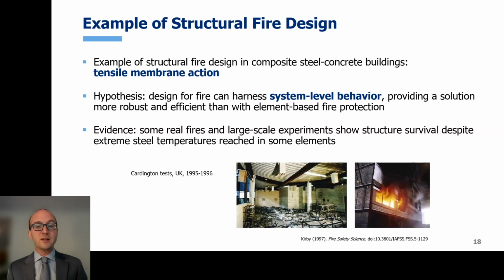So the reason is that structures are not just single beams and single floors and elements in isolation. When we do a standardized furnace test, we look at them in isolation, but in fact, structures are systems or assemblies of these elements working together. So with proper design, it is possible to harness a system-level behavior in this type of composite steel concrete structures.